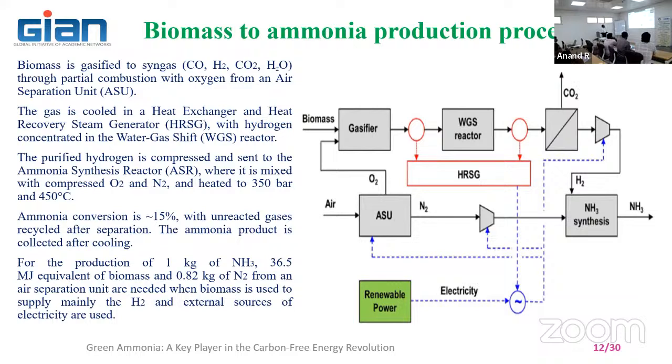Now, as the biomass contains carbon, we need to take care of the carbon capture system. CO and hydrogen are coming out. So the percentage of carbon is going to be lesser than the percentage of carbon that comes out in the form of combustion. That carbon may be converted to carbon monoxide. You can convert it because carbon monoxide is a non-condensable gas. You cannot condense it. So you can use the same carbon monoxide again in the gasifier. You can send it back to the gasifier,